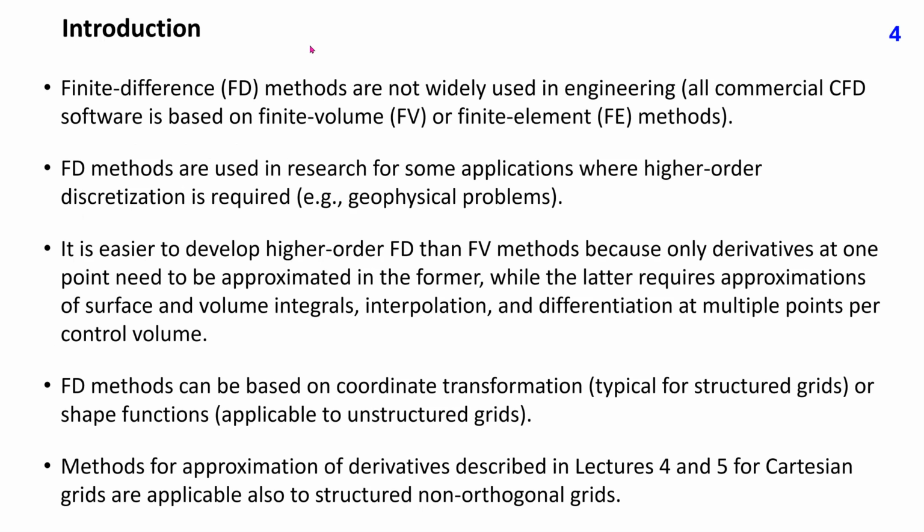Finite difference methods are not widely used in engineering. All commercial CFD software is based on finite volume or finite element methods. However, finite difference methods are used in research for some applications where higher order discretization is required, for example, in geophysical problems. It is much easier to develop higher order finite difference than finite volume methods, because only derivatives at one point need to be approximated in the former, while the latter requires approximations of surface and volume integrals, interpolation, and differentiation at multiple points per control volume.